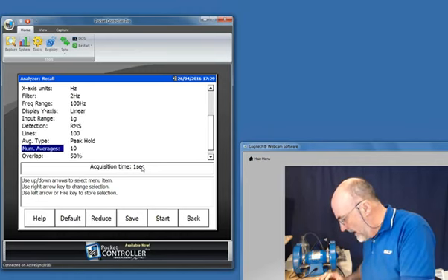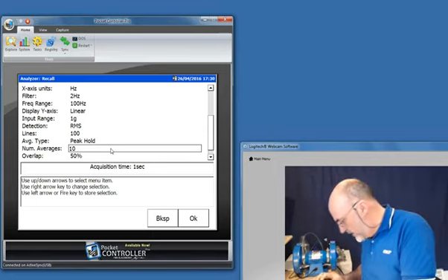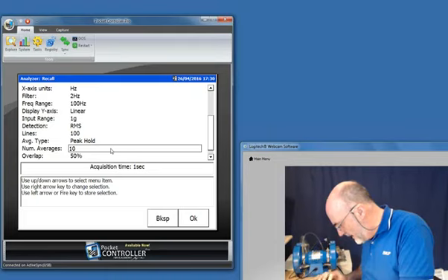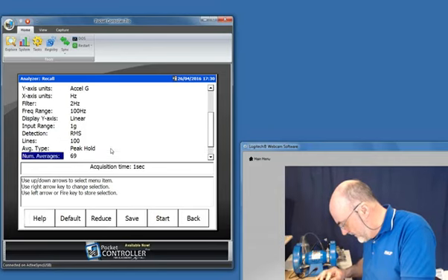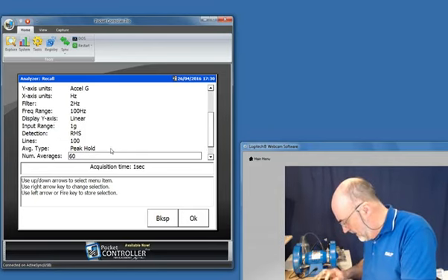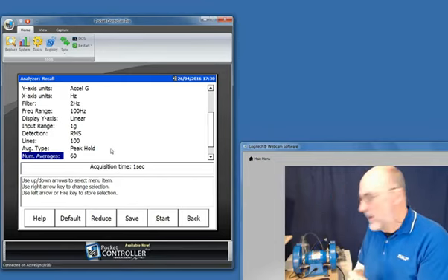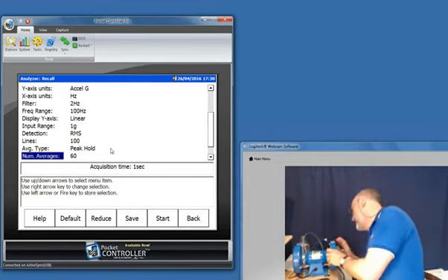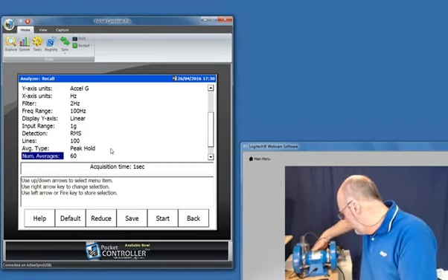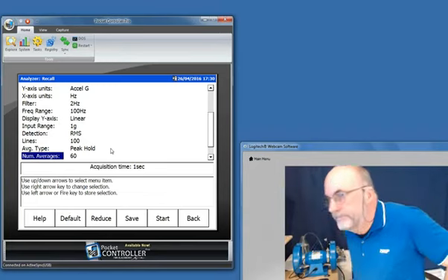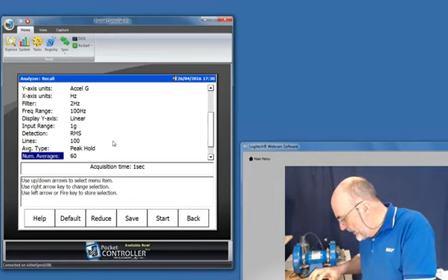Now, one measurement is going to take 1 second. It takes about 40 seconds to run down. So this is an example where I might dial in maybe 60 averages to get that time period. So that should be good. Do a practice spin, nothing trapped. So we'll start the machine. My machine's running up. I press start.